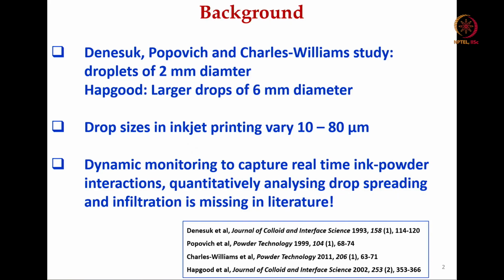So, this binder jet printing has been investigated for quite some time, and there are several researchers who have also provided some understanding on this subject. For example, Denesuk, Popovic and Charles Williams used droplets of 2 millimeter diameter, which is fairly large compared to the components that we are interested in, and Hapgood used larger drops of 6 millimeter in diameter. Typically in today's